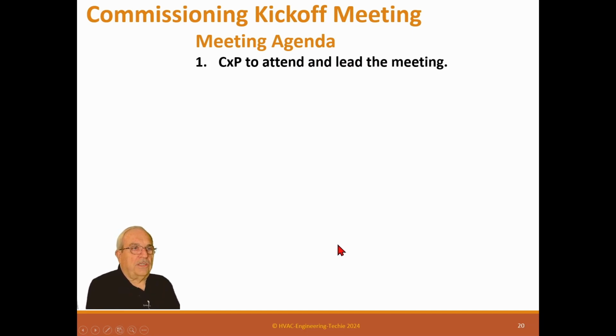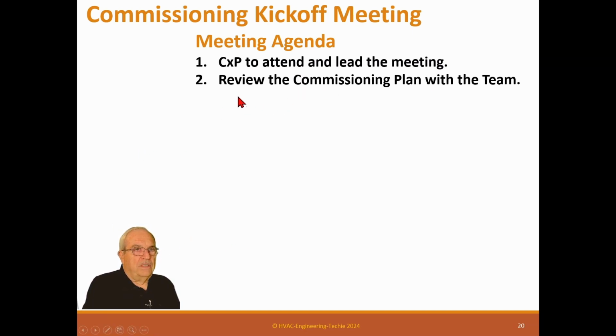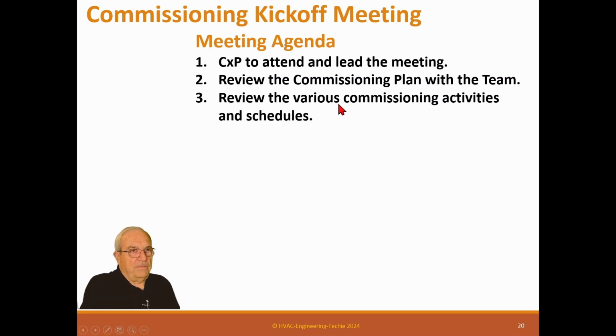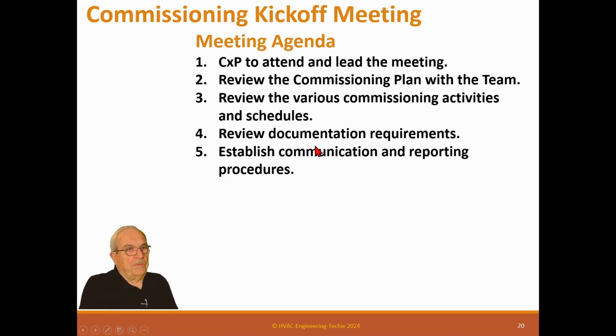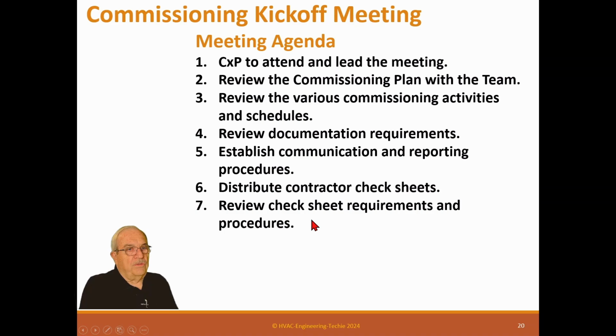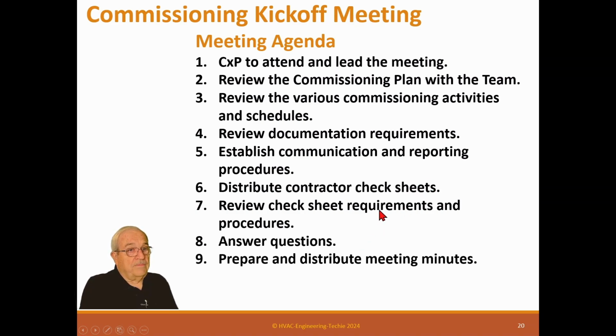Now, the commissioning kickoff meeting is an important event. It's one of the things you have to prepare for. It takes some time. The commissioning professional is to attend and lead the meeting. It's your job. Review the commissioning plan with the team. Review the various commissioning activities and schedules. Review the documentation requirements. Establish communication and reporting procedures. Distribute contractor check sheets. Review the check sheet requirements and procedures. Answer any questions. Prepare and distribute the meeting minutes.